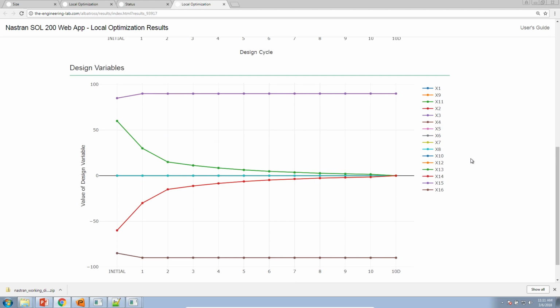And now let's go ahead and see what we have now. So at the very end, I get plies that are 90 degrees for X9 and X15, and for X11 and X13, I get 0 degree plies. So here, if I move a little lower, here you'll see the plies that are 0 degrees.